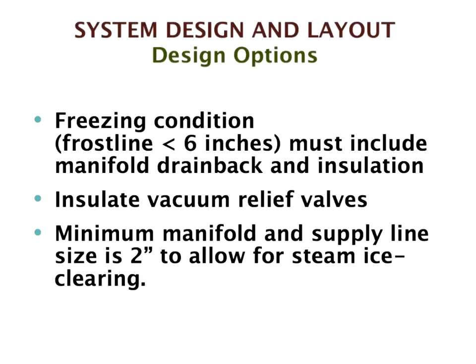Okay, freezing conditions. If the frost line's greater than 6 inches, you must include manifold drainback in installation of the supply lines, the manifolds and the supply lines and the flush lines. You can bury them deep enough below the frost level. It depends on how cold it is.